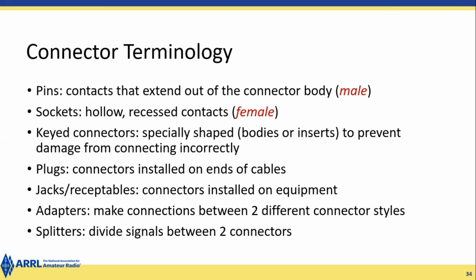Here's some connector technology. Pins are contacts that extend out of the connector body, male. Sockets are hollow recess contacts. We call those the female. Keyed connectors have specially shaped bodies or inserts to prevent damage from connecting incorrectly. So usually connectors are keyed so they can't physically be connected wrong.